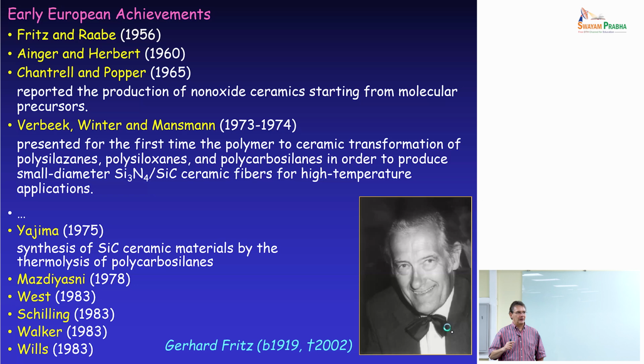And today, all the high-end ceramic fibers used, for instance, in ceramic matrix composites, where you want the fibers to provide toughness to your brittle ceramic material, are made using preceramic polymers for silicon-containing materials, like silicon carbide. For oxides, like mullite, people use sol-gel approaches. 3M has developed some oxide-based fibers using sol-gel.